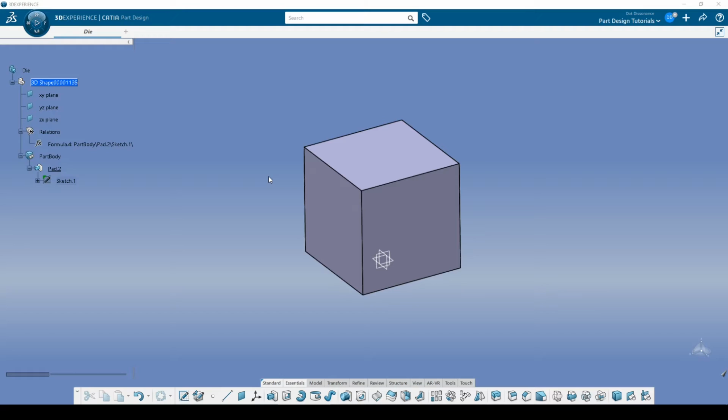So to kind of paint a picture for you really quickly, what we're going to do is we're going to make a thing. We're going to make a word. It's kind of like a variable. We're going to make an element that has a name. We're going to give it a name, something that's good and understandable by us, and then we're going to give a dimension to it. We're going to give a number, a value, or something. Now, that in itself won't do anything. We then go find certain elements that we want to be the same as that, and we link them. We tie them together. And then what you'll be able to do is change the one thing and possibly have many different things change. It's extraordinarily helpful.